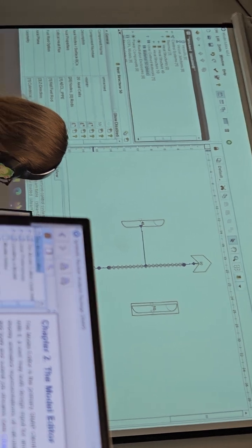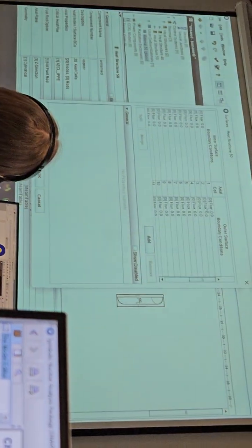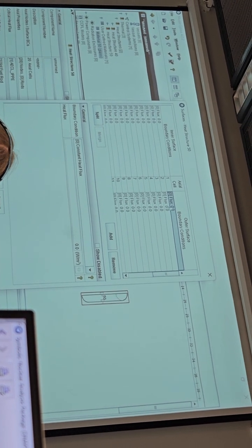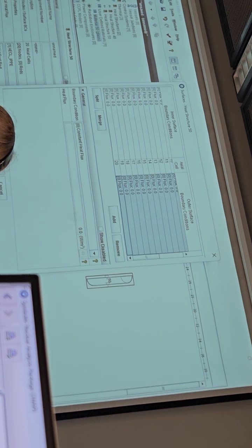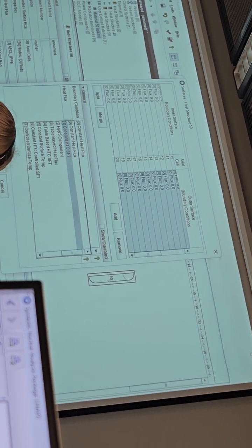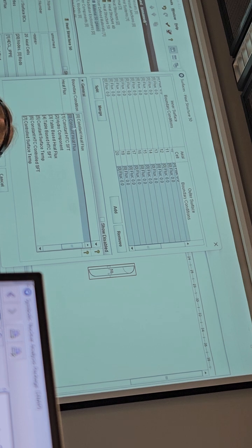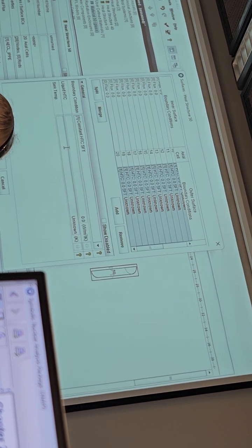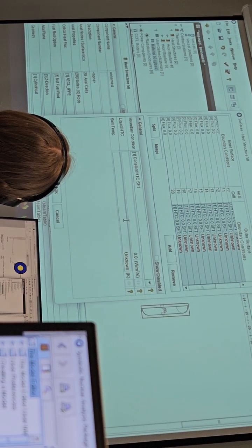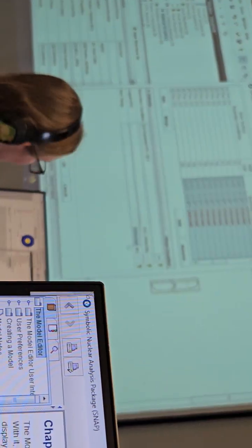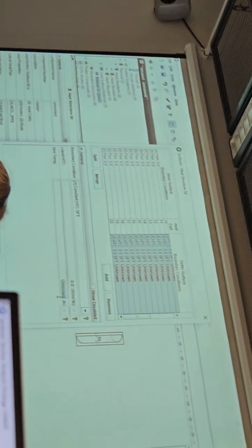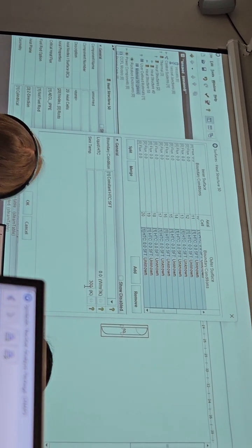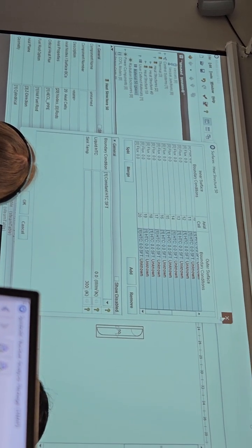Here in the axial nodes and surface boundary conditions, you can click here and you see on the right side the outer surface boundary condition. You can easily choose all the cells and then for the outer boundary condition just change to the constant heat transfer coefficient and surface temperature. So then we need to define two parameters. Sink temperature, it is atmospheric air temperature equal to 300 kelvins, as it is defined in the menu. If you open that menu, okay, just a moment.